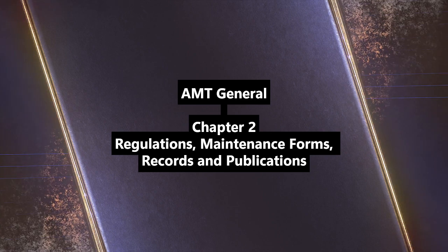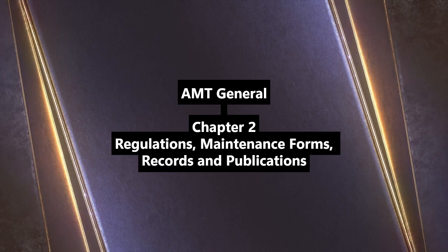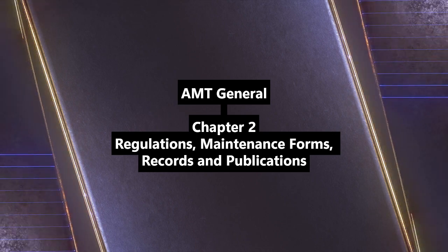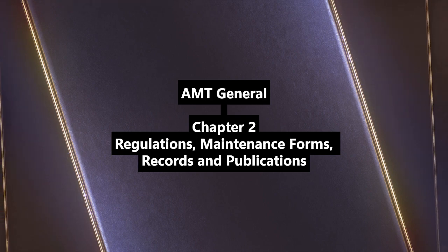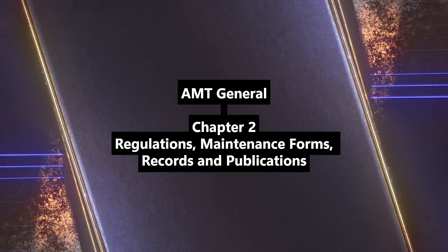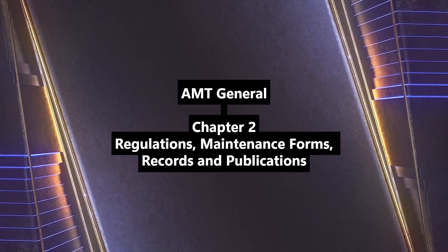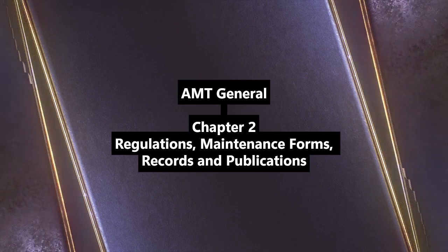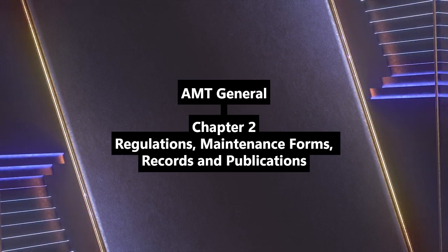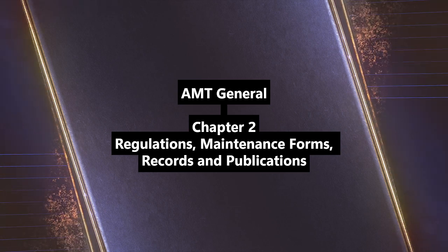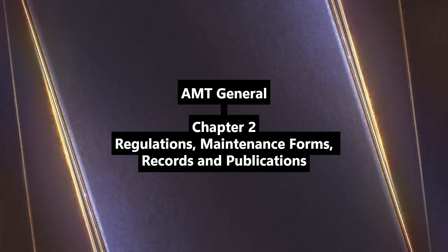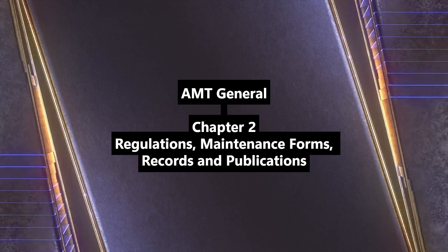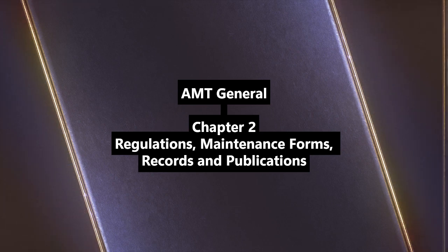Powerful. Section 43.13, performance rules, how you actually do the work. Right. It says you must use the manufacturer's manual, ICA, or other FAA acceptable methods like AC 43.13-1 and 43.13-2, especially for smaller, non-pressurized planes, unless 43.16 applies. And use the right tools. Yes. Proper tools, equipment, and testing apparatus are required. You can use equivalent test gear if the FAA finds it acceptable, but proving equivalence is on you. Air carriers can use their approved manuals.